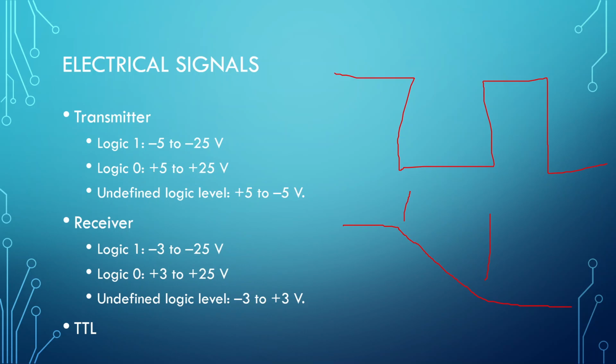When we're communicating over long distances, a few hundred feet or maybe even more, I don't know the range for serial off the top of my head, I think I might have that on a later slide. But we're covering long distances, so we need high voltages so we can have power. However, computer processors, anyone know what voltage those run at? Your standard CPU is like 1.2 volts or something like that. The voltages there are extremely low. One of the reasons I like these lower voltages is that when they transition, there's a much smaller distance to go from a 1 to a 0. It means they can do it quicker.